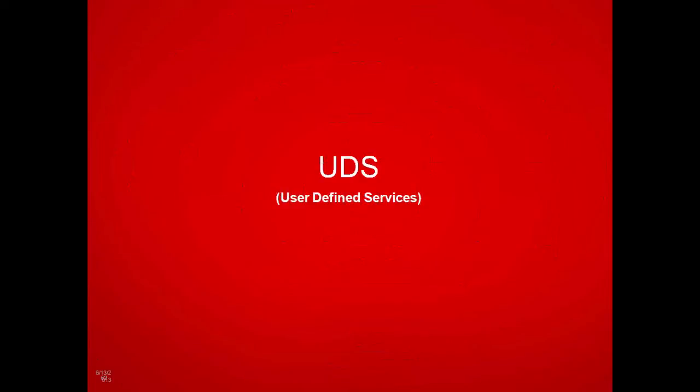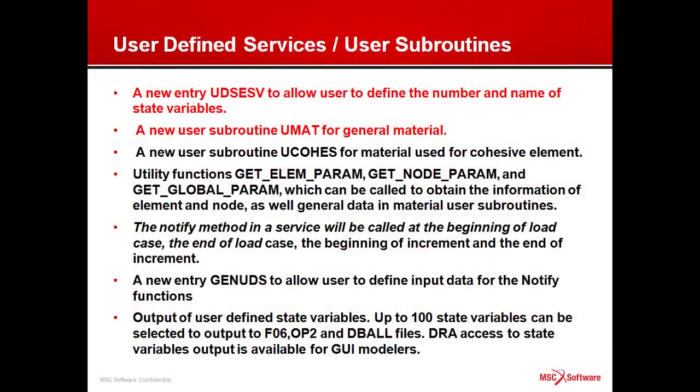The next topic I want to talk about is UDS, or User-Defined Services. User-Defined Services are our mechanism to allow you to customize the product through user subroutines. There have been several advances in the use of these user subroutines in this release, and there will be continued improvements in the subsequent release as well. They break up into really three groups. One is we've introduced a way to have state variables in the system and allow those state variables to be used in the user subroutines. I'll get to that a little bit later.